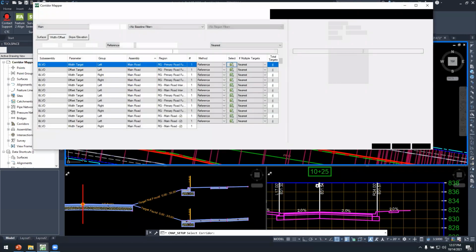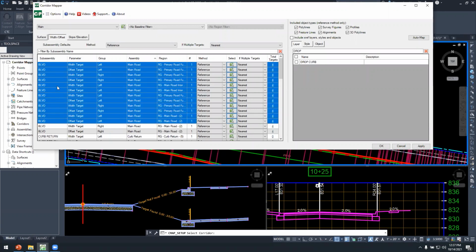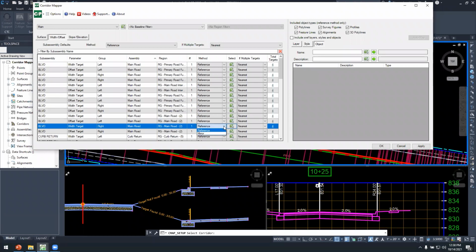I can link subassemblies, and notice I've been grabbing multiple subassemblies at once. We can't do that natively at all. I can grab a whole set of them at once and link them to any property. There's a 3rd tab over here where I can link by object names or object descriptions. And then under the reference column, I can also choose to mirror one set of subassemblies to another, say, parent subassembly, allowing you to basically replicate targeting scenarios really fast.